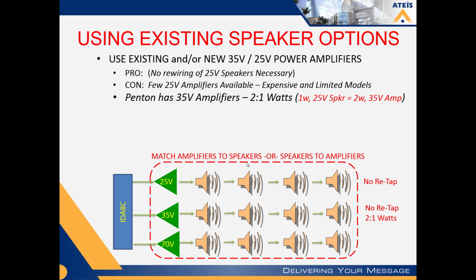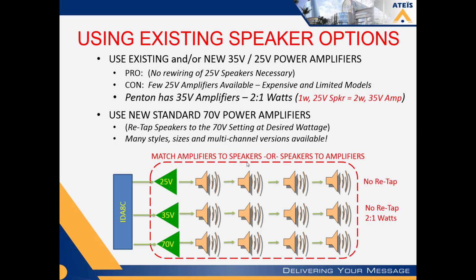The other option is if you're going to totally rework the zones for all your common area speakers. Let's just say, for example, you have a switch bank system and they have a dozen or more common area circuits coming back on switch banks, with only 8 or 10 speakers on each one to keep it under the intercom amplifier talkback amp load.